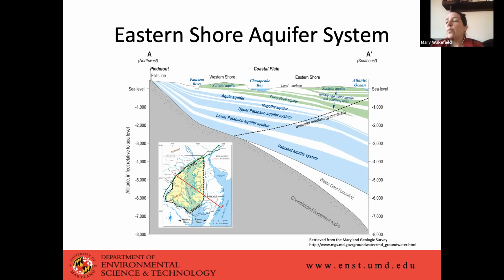So as you withdraw from the aquifers, you have the potential to compact any clay-based aquifer system, which means it cannot be renewed. You also then begin land subsidence, because as that land compacts, it goes down. So you can see that we don't have a lot of groundwater to work with, and it's really important to remember that this water is used for drinking water almost exclusively out on the Eastern Shore.